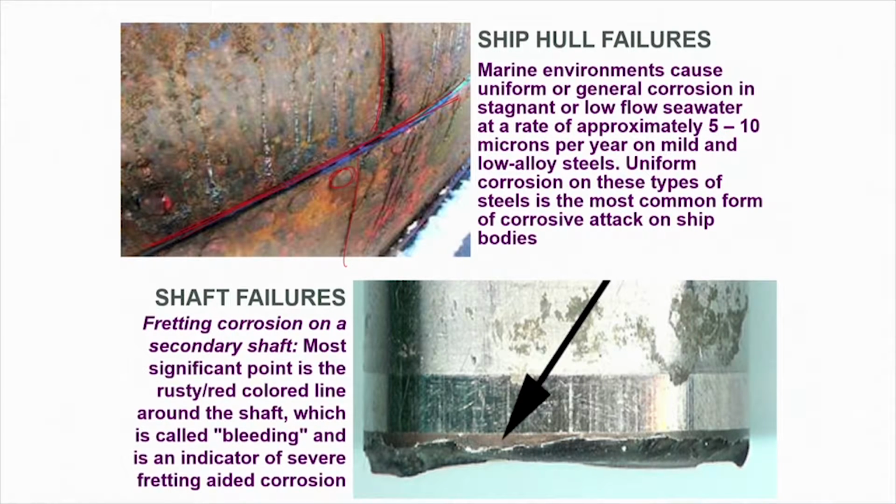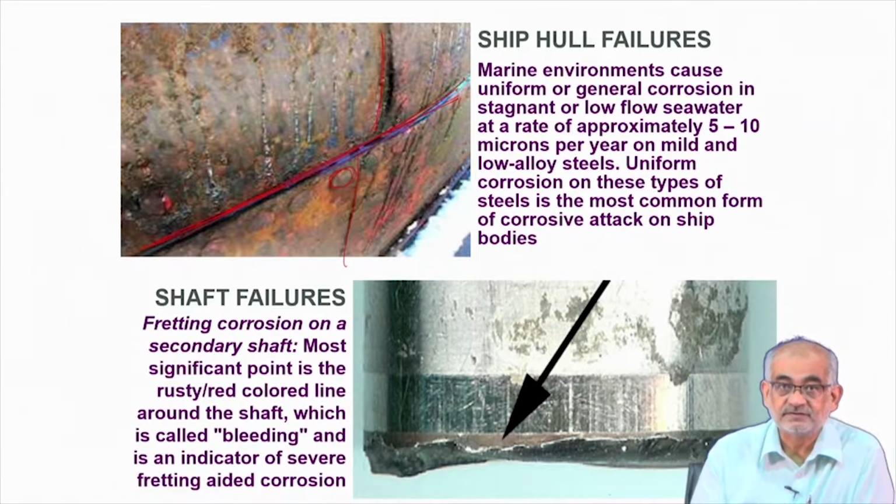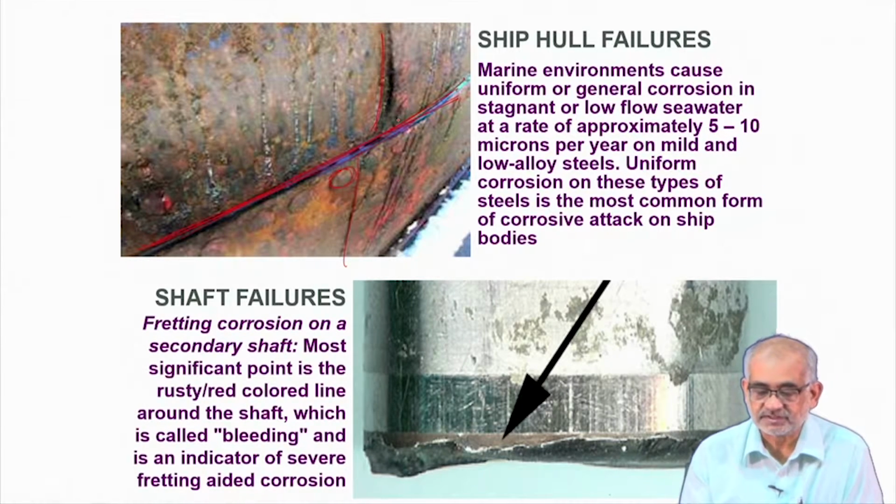So corrosion can occur, and may be particularly severe, along these joints, and that's very dangerous, because if the corrosion at these joints actually penetrates, then obviously there will be puncturing of the sheet, and obviously the ship cannot remain floating in the water anymore.